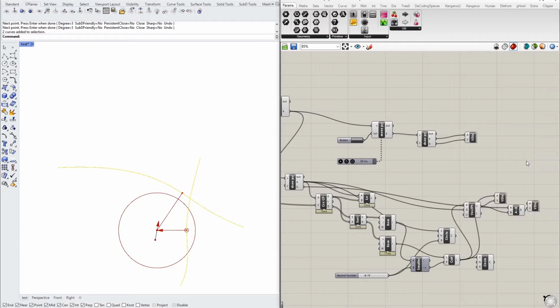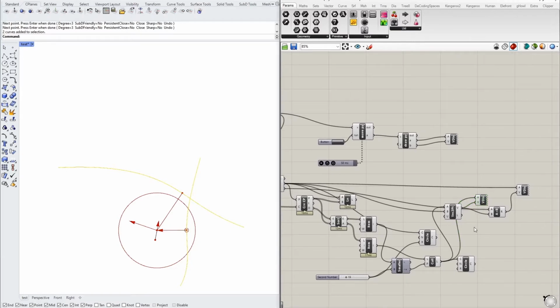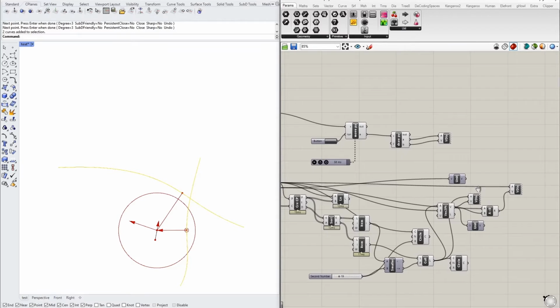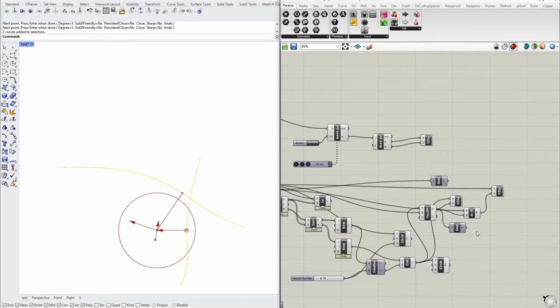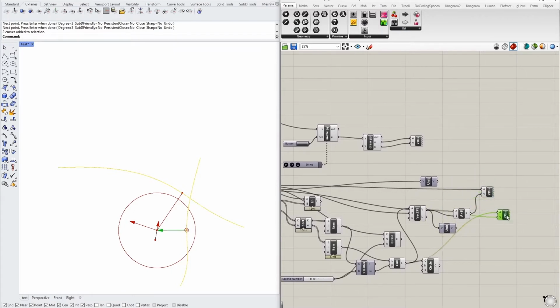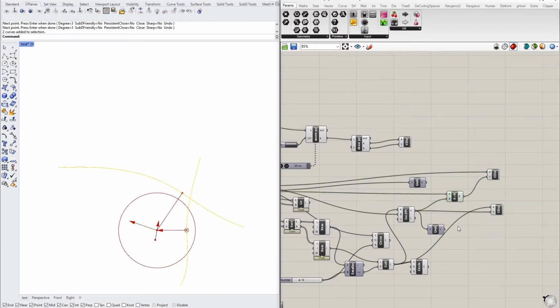And let's visualize it with a vector display. We can control the influence by adjusting the magnitude and amplitude of this vector from the closest point to the Boid position. In this example, we will unitize both of the vectors. When we unitize, sometimes called normalize a vector, we keep the direction, but set its magnitude to 1 unit. And we can set a specific value for the vector from the closest point to the Boid position by multiplying the unit vector.